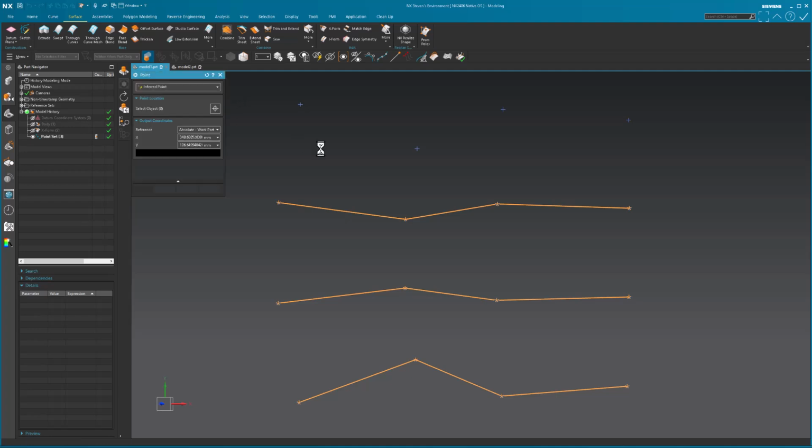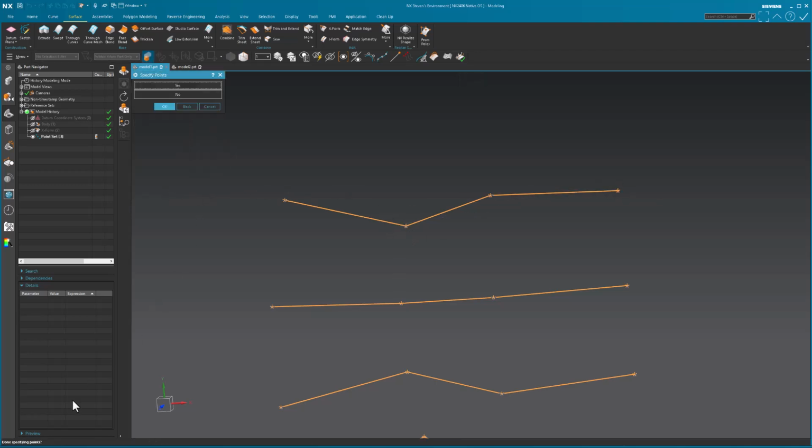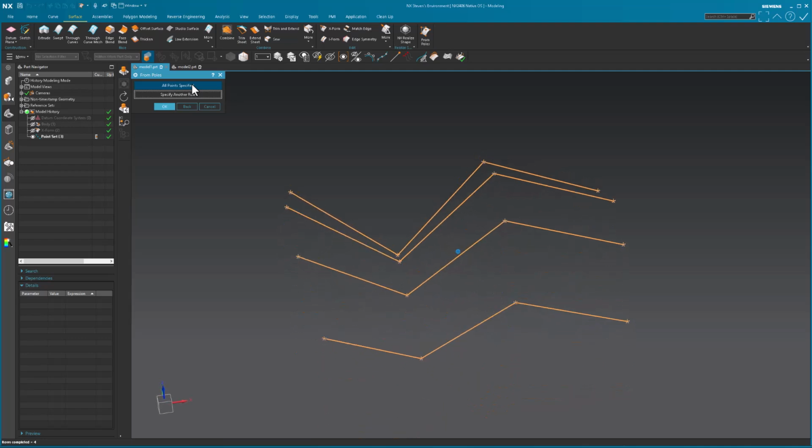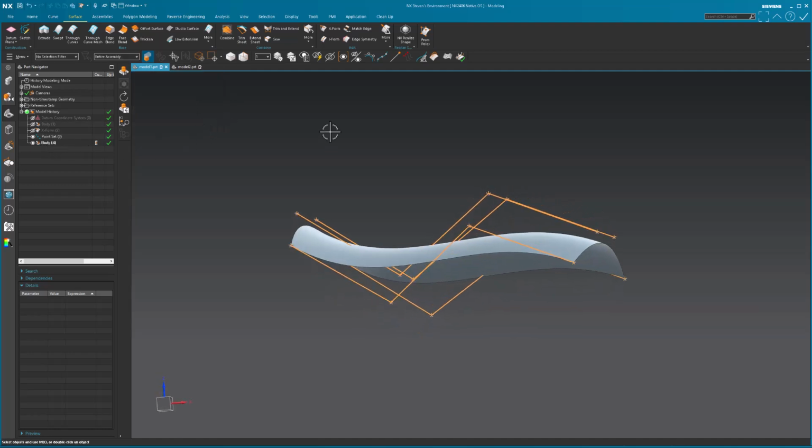Specify another row. 1, 2, 3, 4. I'm done. Yes, I am done. Specify another row. All points specified. Now watch what magically happens as soon as I hit that. I get a surface. Okay, there's my body. Notice there's no history there. Before I refresh the screen, I'm going to show my X-form.